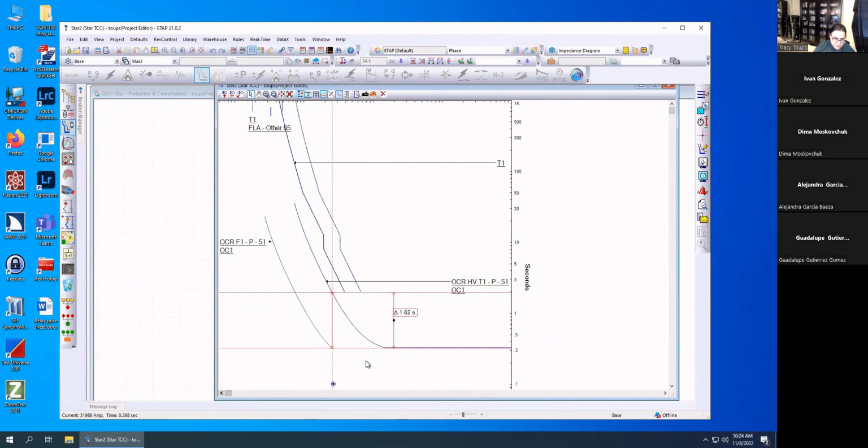And notice, let's go to the max here. We got 1.62. We could then move the secondary curve to, I think I said 2 seconds or maybe 1.5 seconds, I believe. Let me double check. Yeah, 1.5 seconds for the next one, just to give us a little more leeway again. So we could change this, move it around a little bit till we get that 1.5 second delay just about right here. So 1.4 seconds, pretty good.